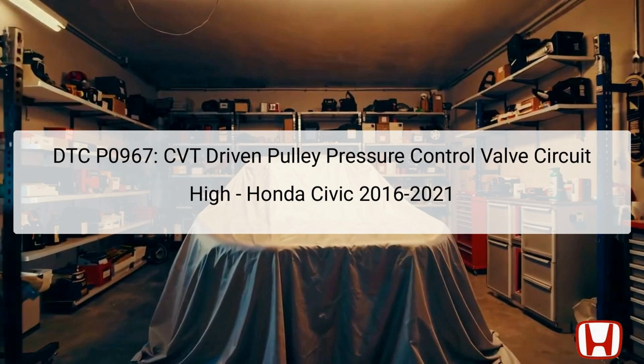When a malfunction occurs, such as a short circuit, the TCM will detect a discrepancy between the commanded and measured currents, activating the diagnostic trouble code, DTC. The DTC indicates that the pressure control valve may not be functioning correctly, which impacts overall transmission performance. Understanding this code helps in diagnosing potential issues with the transmission system.